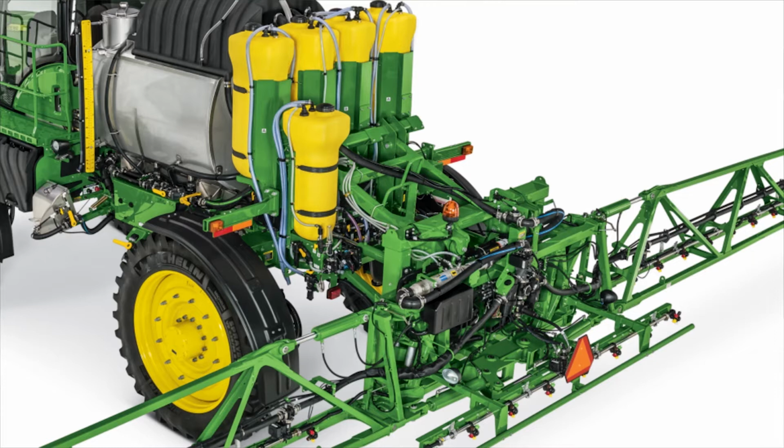Now these pumps are located on the back part of the machine behind the solution tank. Our R4044 and R4060 are not compatible with direct injection. Those essentially sit on chassis that are similar to other models, but they stretch the solution tank a little longer, take up the spot where direct injection would sit. These systems are also equipped with flush valves, so we can flush our pumps from inside of the cab, and that will pull water from our clean rinse tank through the pump, and we spray it out the boom or catch it if we want to as well.